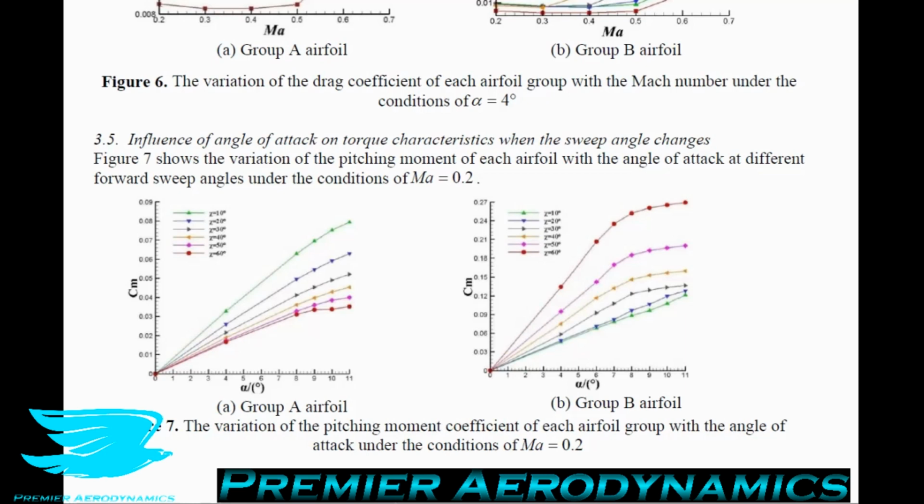Alternatively, if the aircraft has a negative pitching moment, then at an angle of attack of, let's say, 5 degrees, flying around, the aircraft naturally wants to pitch down, so nose down. That means that the lift that you produce will naturally drop, and that's stable because now you're going to an angle of attack of 0 degrees. You may not be able to fly, but you can glide, and that's far more stable than losing lift altogether from pitching too high. So that's why we want a negative pitching moment coefficient.